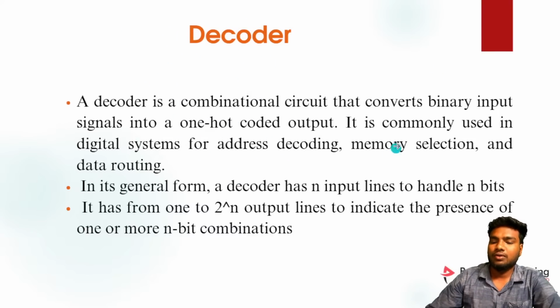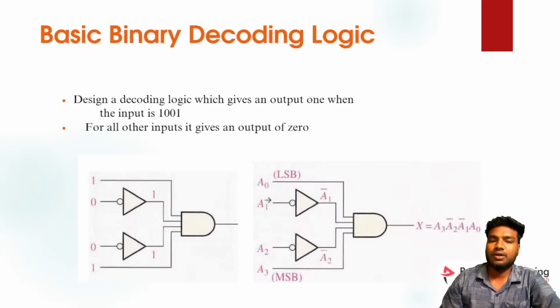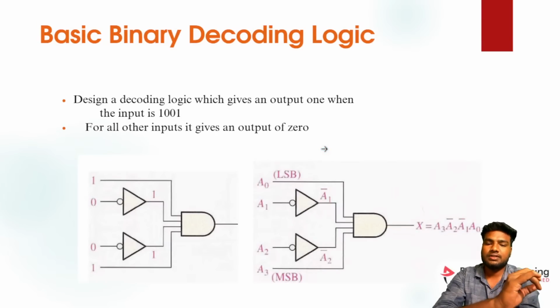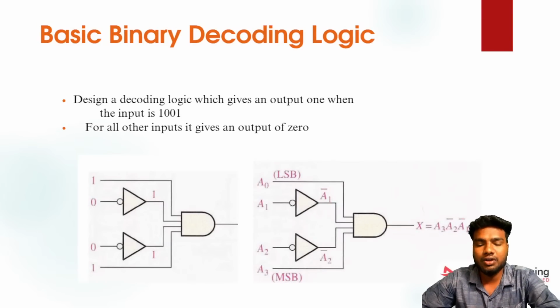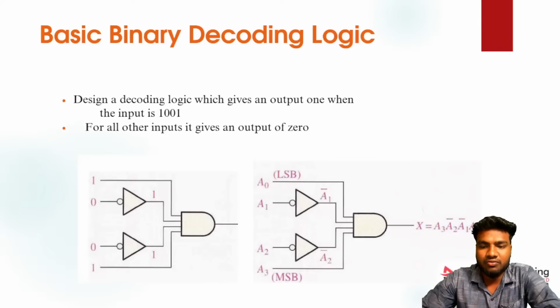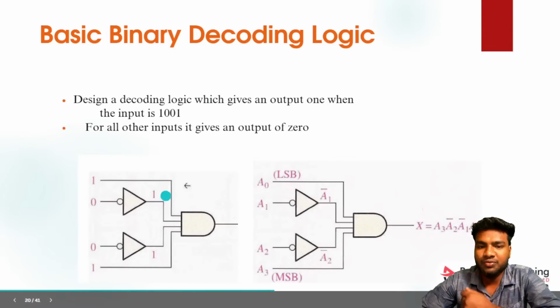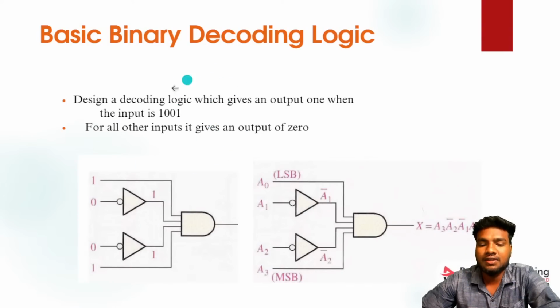So we'll move to the decoder operations. This is a general question, and it is also an interview question. If you are in an interview, you can receive a question like: design a decoding logic which gives an output of 1 when the inputs are 1 0 0 1.